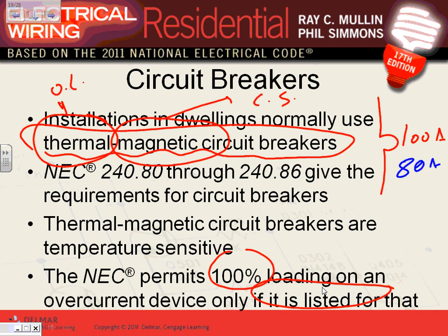So circuit breakers, guys, unless they're listed, which they make them, it makes more sense to start using 100% rated circuit breakers if you're dealing with 600 amp to 1,000 amp or higher. That's where we start using them. So I have a 4,000 amp circuit breaker that will carry continuously forever 4,000 amp.